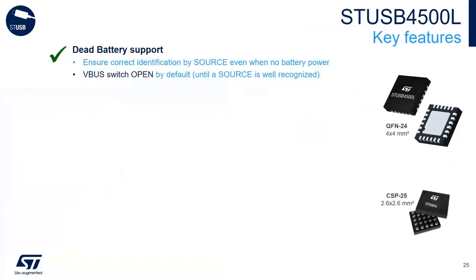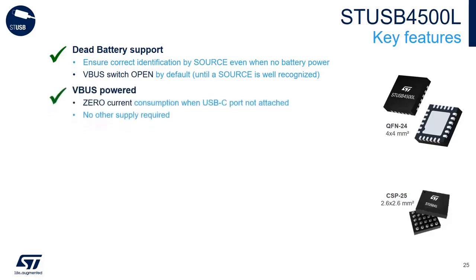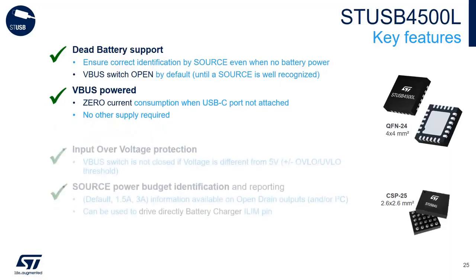In short, here are the features supported. Dead battery support. That means no battery or microcontroller is required to run the ST-USB4500L. It provides safe and ultra-fast power-up. It is powered directly from VBus, so there's zero leakage at all on the application battery, and that extends the battery lifetime of the device.